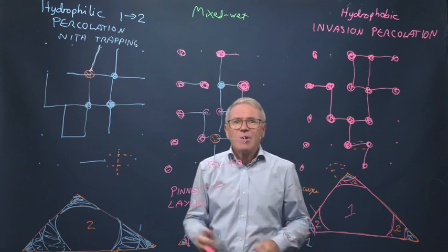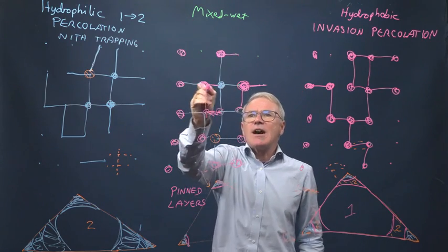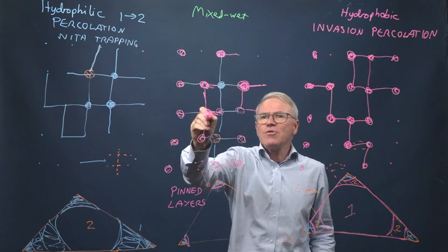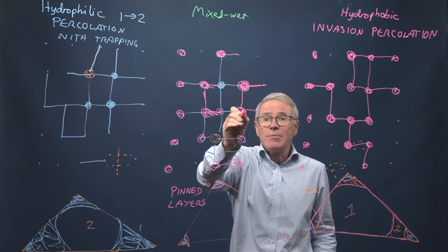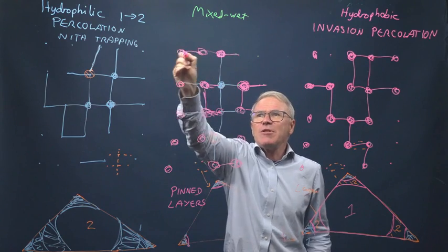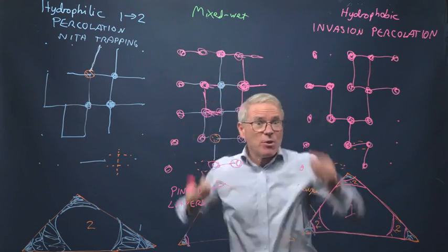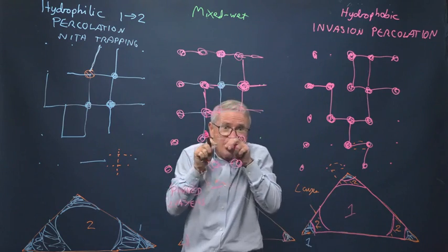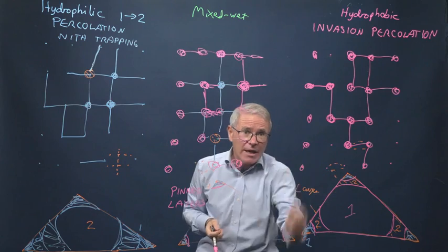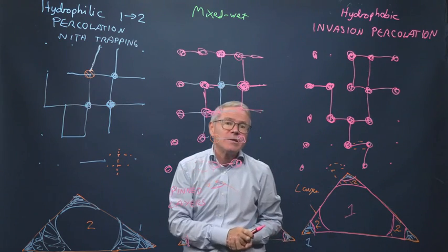Now, eventually, what happens is, okay, now I connect in a wide pore, I just have one more connection, and suddenly I'm away, all right? Because now I've got a connection through the pore space with large elements, okay, some of the narrower elements here, but basically, once the hydrophobic regions get going, right, I'm in good shape. I actually fill some of the wider regions. So the relative permeability is almost zero, almost zero, almost zero. Then you reach the percolation threshold, you connect, and whack, up goes the relative permeability.